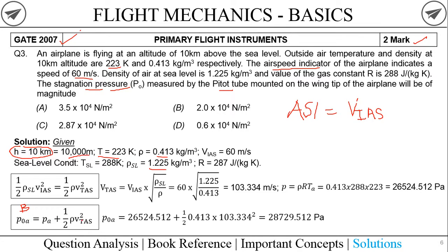So in a similar case, when we substitute the velocity to be zero, this whole term on the left hand side cancels out, and we will be remaining with P naught. So this P naught is the stagnation pressure. So for this, we need to find the stagnation pressure.